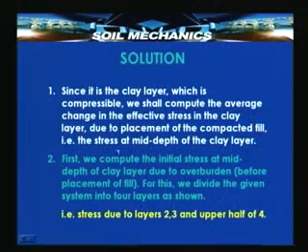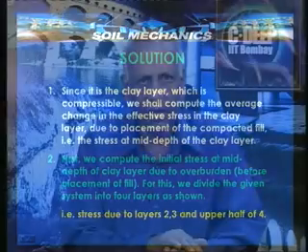So, we shall compute the average change in the effective stress in the clay layer due to placement of the compacted fill, that is, the stress at mid depth of the clay layer. First, we compute the initial stress that is already existing before placement of the fill, again at the mid depth of the clay layer.